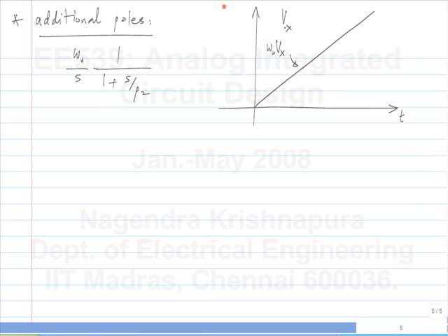So, first of all, why do you say ramp plus negative exponential? Meaning ramp plus something like this. So, the result will be, here it is constant. Is it going to be like this? First of all, how did you say ramp plus negative exponential? The standard way to solve this, you want to find the step response of this, right? So, you can multiply this by 1 over s and find it, or you can basically resolve it into terms which have distinct poles in them. So, each pole has a separate term and you add up all the responses. That's how you do it.